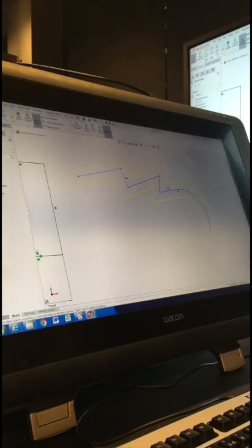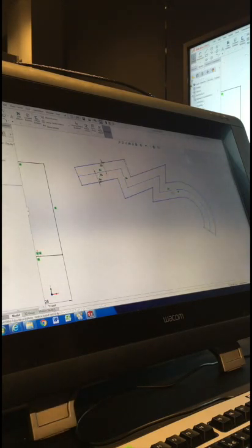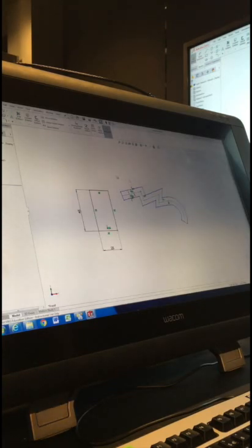And this way you can make that cut very easy. So you can go base geometry, okay. You can see how the original line is now construction, and the offset bit and the lines on the outside are normal lines that I can then use to cut or extrude. All right, so that's how the offset tool works.